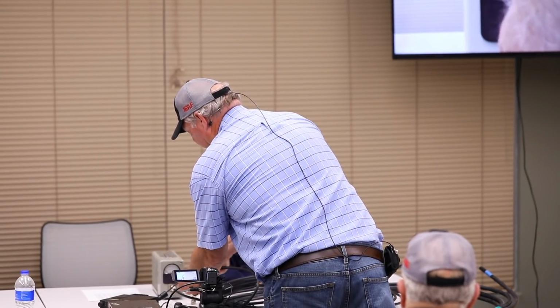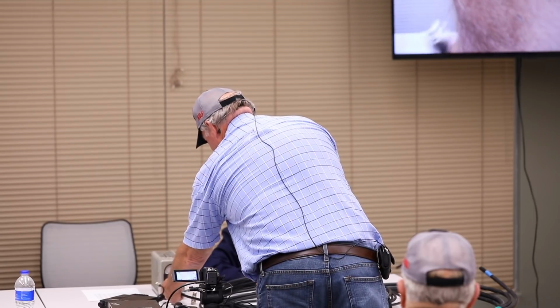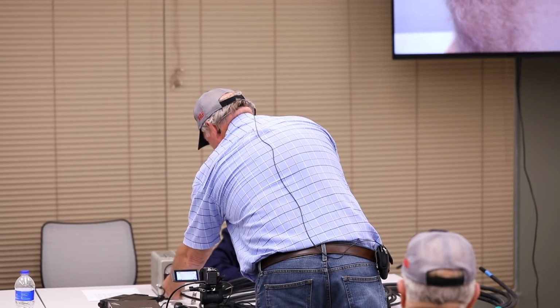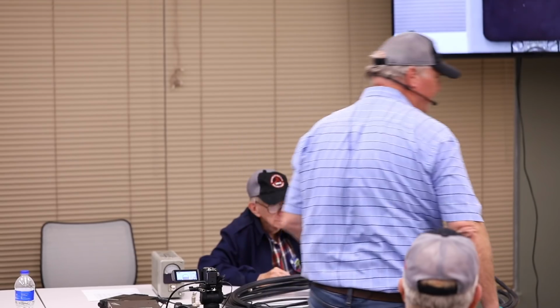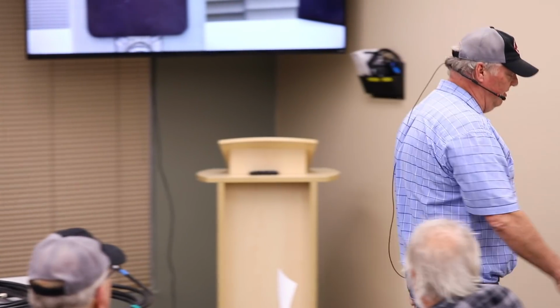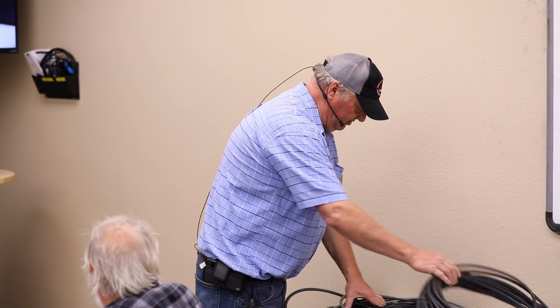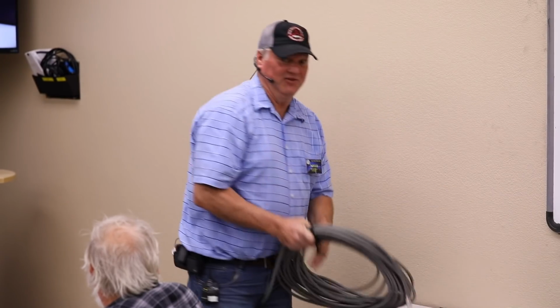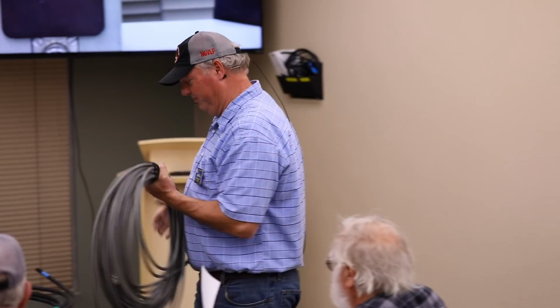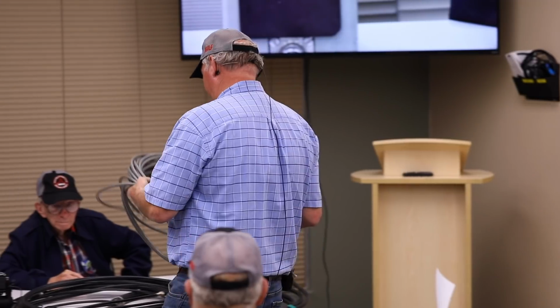So let's look and see what it is over here. We could do another experiment with this stuff, but we won't do it tonight. You could put an SWR meter in there behind your radio and see what it's doing, because it's going to have some reflected power because it's the wrong coax.